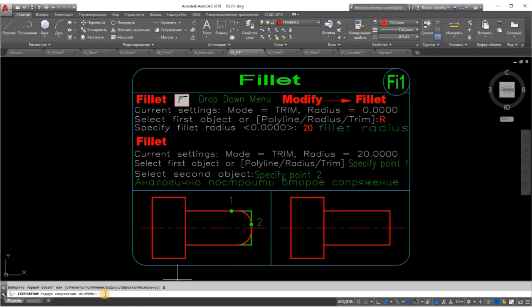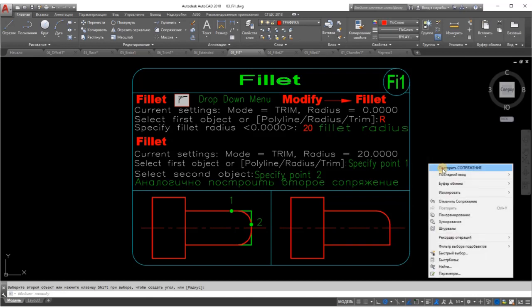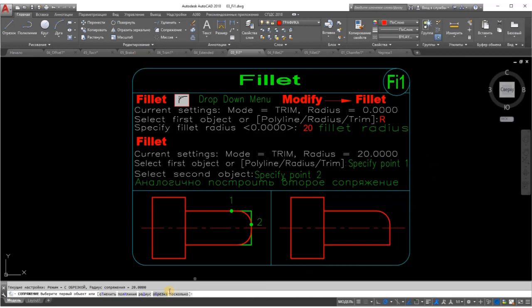If the fillet radius or the chamfer distances don't look right in the preview, you can change their values before completing the command. The following steps describe how to use the fillet command. The chamfer command works similarly except that instead of specifying a fillet radius, you specify either two chamfer distances or a chamfer length and angle.